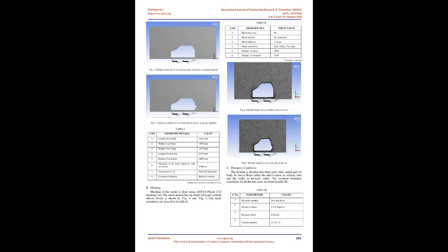Yuan Cheng et al. [7] investigated that there is a critical value of spoiler height where the hatchback model would experience a dramatic increase in its aerodynamic forces, associated with the change in the flow topology above its slanted rear surface. Since downforce is proportional to the tractive force, it is imperative for the ride's stability and safety. Furthermore, high downforce performance is vital during cornering when the vehicle needs sufficient traction to pass the curve without slipping. Snehitawal et al. [8] reveal that the drag force is the unwanted thing which normally acts against the drive force of the car. The downforce is useful to maintain the race car on the ground.